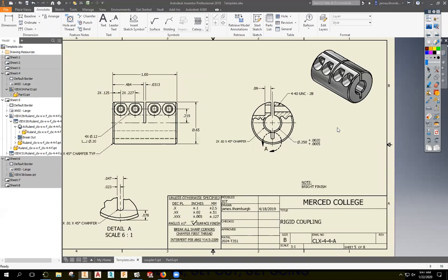Yeah. Those hidden lines that show the threads. Yeah, because that's showing us that it's the thread. Those aren't really hidden lines. That's the note for the thread. That's how you show threads. Okay, so that might be how I do this one. So I kind of took what I did yesterday, adapted a little bit. Now I can include a section and kind of call out this area a little bit better.